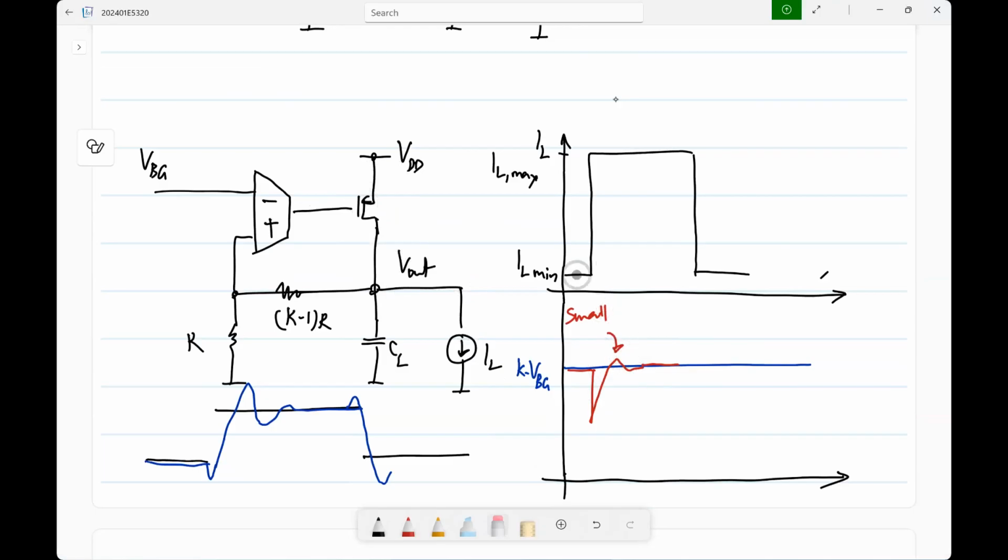So basically, if it's a very small signal step, of course, you have the operating point and there you calculate. What I want to distinguish is the two cases. If you have a small step, a positive step and a negative step, the response will be equal and opposite, right? That is linear. What I was trying to point out is this can be quite nonlinear, because what happens now when the current steps down?